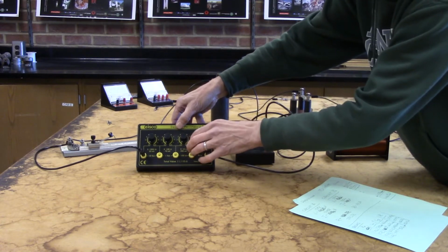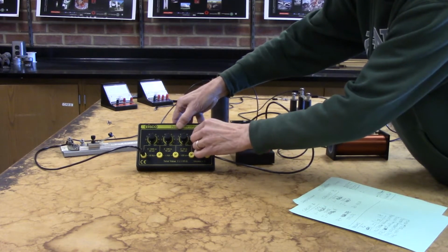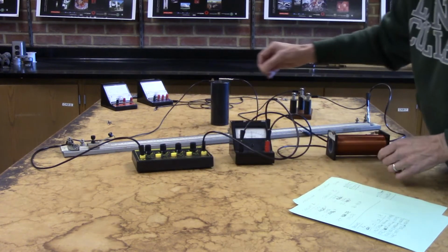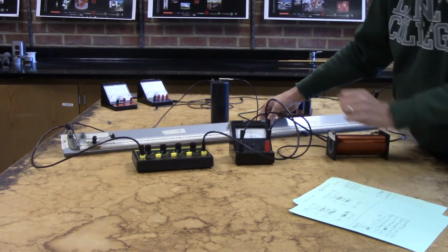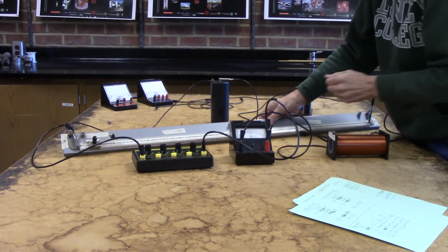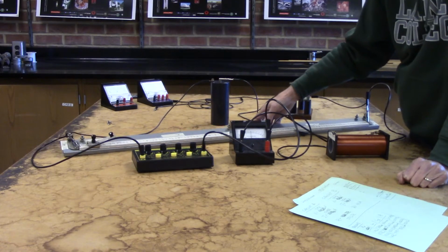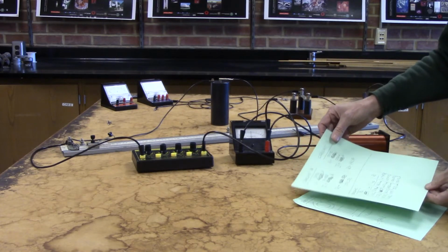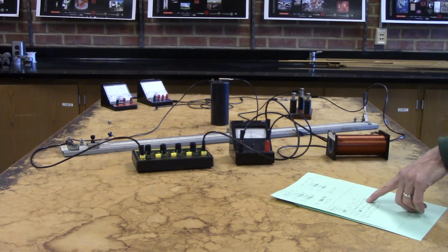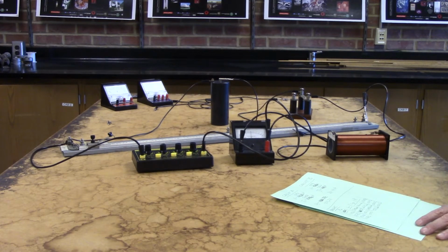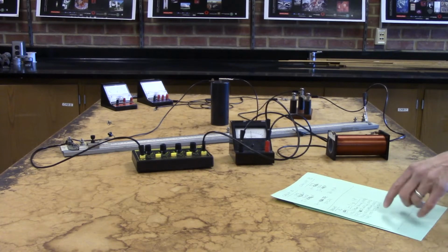So what I'm doing is I'm adjusting in the resistance box. I've gone from 1 ohm to 2 ohms to 3 ohms to 4 ohms. Now as the resistance increases here, then on this R2, R3 wire, the balance point is going to shift farther to the right. Okay, and so what I've done is I've done a series of those 4 measurements, and the resistances are coming out pretty close. I'm getting resistances of 1.17, 1.27, 1.30, 1.31. So that first measurement is a little off from the others, but the last 3 are pretty similar.